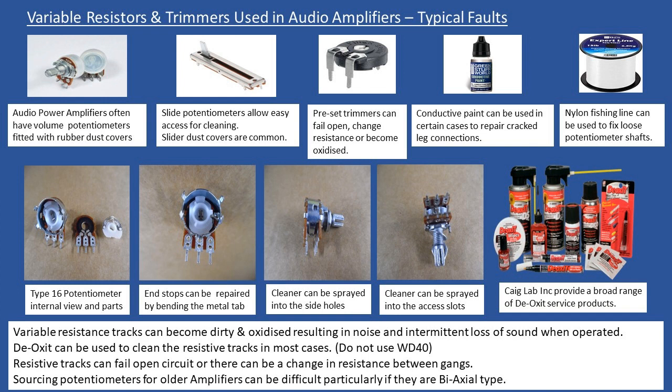open circuit, right? If they're not open circuit and all is good, what you can do is again spray in DeoxIT, and then with the amplifier switched off, don't do it with it switched on, because obviously this is a bias trimmer, you can rotate it backwards and forwards a number of times, leave it for a few minutes, repeat again, return it to the same position that it was in before, and then you can do the final adjustment for the trimmer.